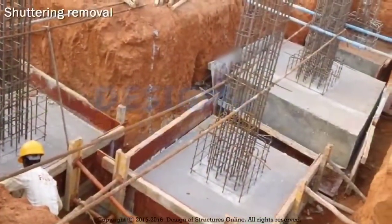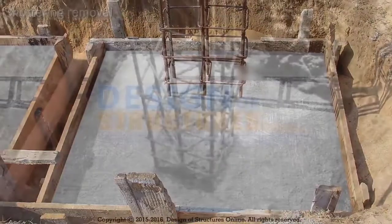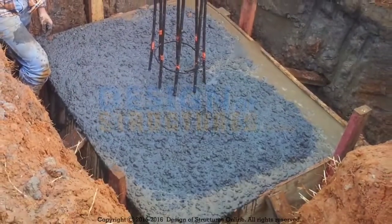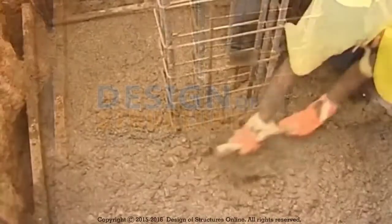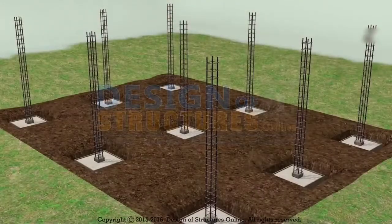Shuttering removal. The formwork removal procedure should be supervised by the engineer to ensure that the quality of hardened concrete in the structural member is good. That is, it should be free from or have minimum casting defects such as honeycombing, size and shape defects, etc. These defects in concrete influence the strength and stability of the structure, thus immediate repair works can be done or the members can be rejected.